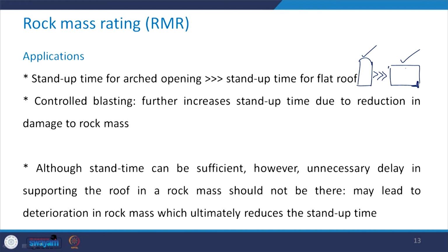You have seen that stand up time can be as large as 20 years for a 15 meter span of the tunnel in case of a very good quality rock mass. Although you have sufficient stand up time, unnecessarily we should not wait till the end of that time in order to provide the support system in the rock mass.